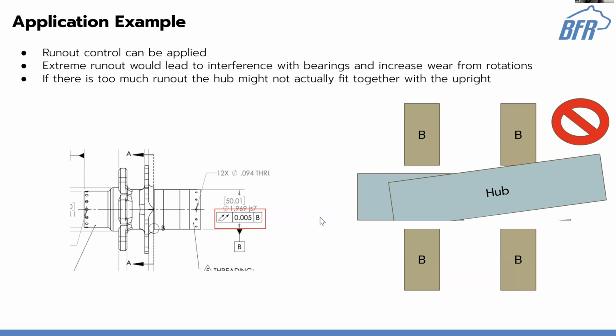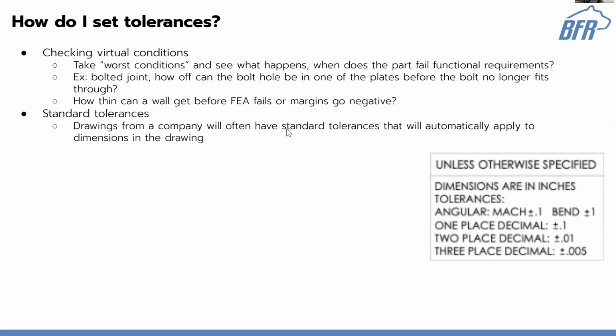So, how do you set tolerances? That's a good question. Anywhere you go, honestly, there are a lot of examples of where tolerances are set very poorly. Half of my job this summer was, hey, this part is out of tolerance, but I still need to see if it's okay, because it seems like they set the tolerance very arbitrarily. I don't see anything that's actually dictating this, but they put a super tight tolerance on it for some reason, and I just want to confirm the part is still going to be usable.